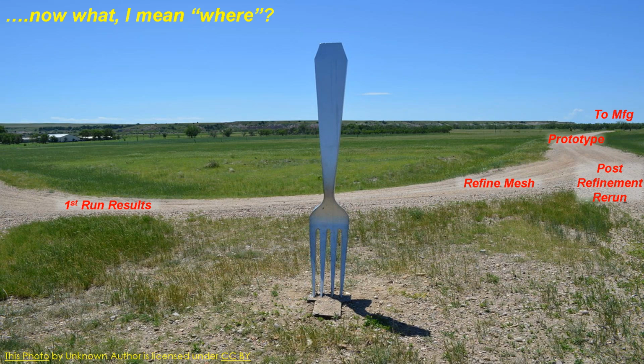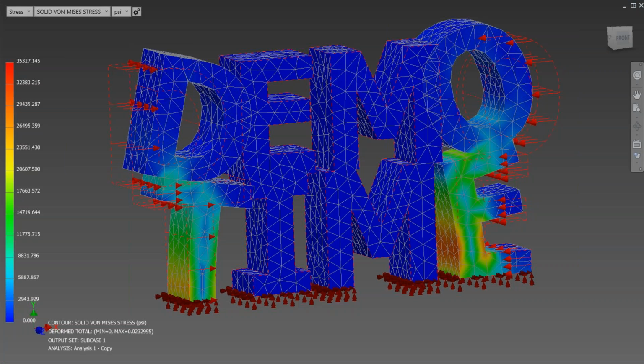So initially, you're going to tweak Nastran as you're learning it and adjusting. You're going to tweak it to where the results that Nastran is giving you match what you've already seen for products out in the field, match the expected results. Once you have that, then you've got the confidence on designing new products, and you can use Nastran to run those calculations, get confidence there, and build one prototype before you go to manufacture. That's the whole goal of all this, to reduce the number of prototypes.